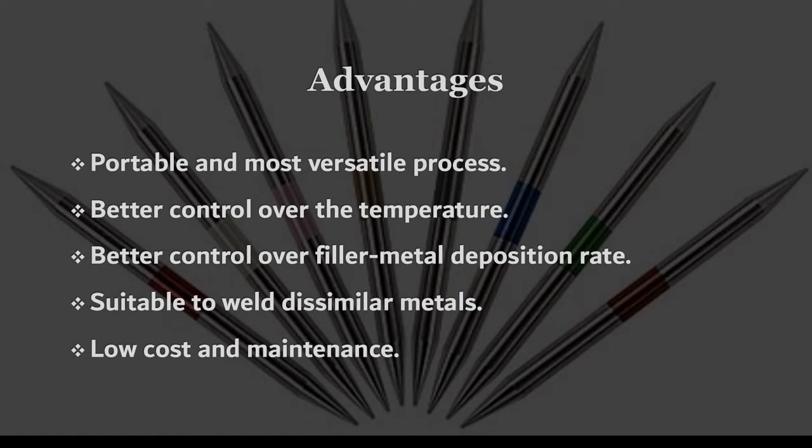There are several advantages of oxyfuel gas welding. The first is that it is a portable and most versatile process. The next, better control over the temperature. Then, better control over filler metal deposition rate. And suitable to weld dissimilar metals. And the last is low cost and maintenance.